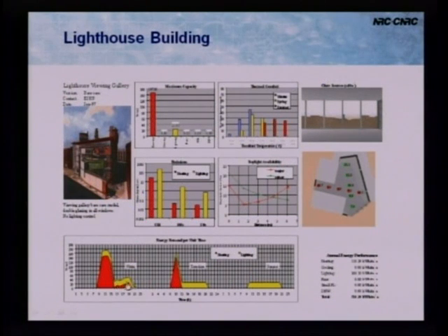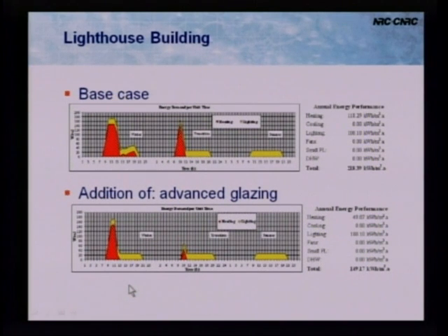Looking at the profile for energy use at different times of the year, we've got a winter day here, we've got a day from spring and a day from summer. So we can see, just going back through here, there's no lighting control, so the lights are on all day, every day. So we've got this lighting gain every day. We've got heating in the morning in spring, and then the temperature gets a little bit warmer in spring, so the heating goes off. In winter, we've got large heating load in the morning, and then there's residual heating required later in the day. So we started looking at